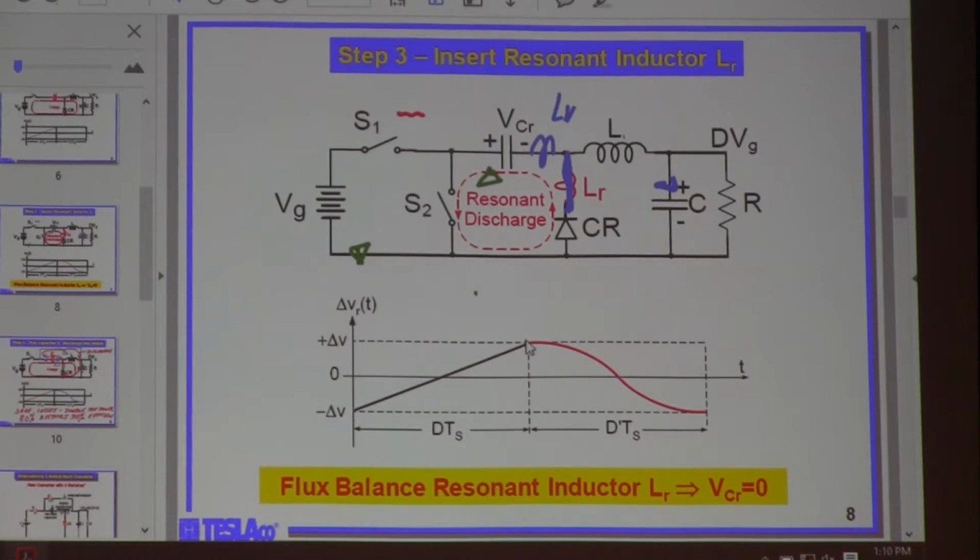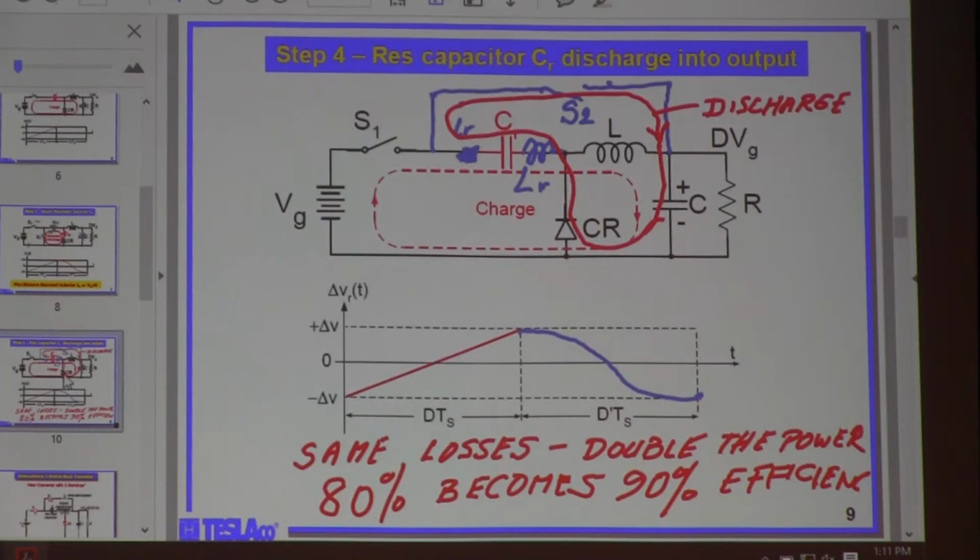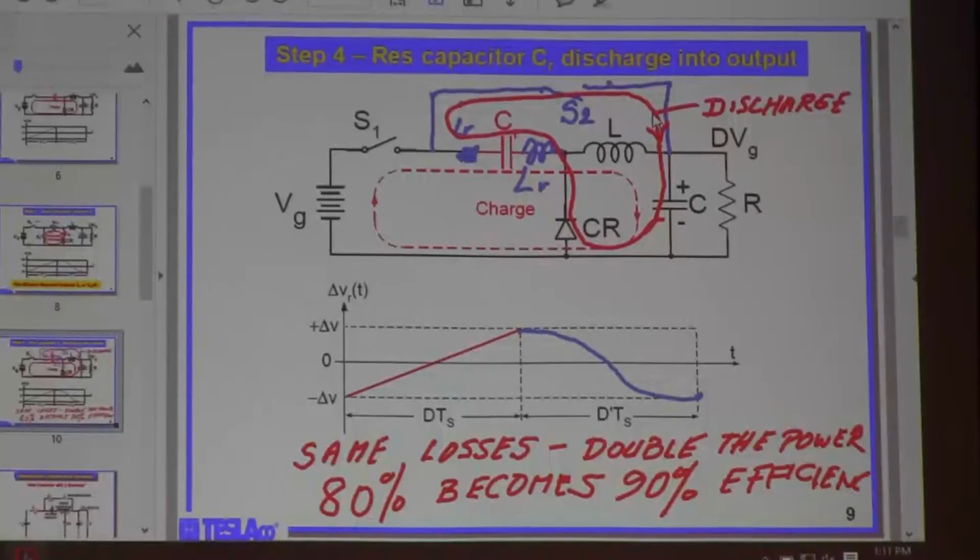The inductor current here is rising linearly, a resonant current, and then is discharging in a resonant way, and both points are well connected. There's nothing happening there. It's smooth, right? Okay, so we go to the next one. Here it is. This is what I just told you. The switch is moved from here into the output. And here all the charge is moved to the output, right?